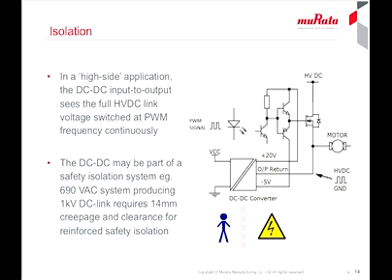For example, the Murata MGJ2 series is tested in production at 5.2 kV and has been shown to work reliably with 3 kV continuously across its barrier. However, if it is part of a safety isolation system needing reinforced rating, the high voltage DC allowed is just 210 volts. This is because of the safety agency evaluation of the internal construction of the converter. If higher levels of reinforced safety isolation are needed, you can choose other parts in the Murata range.